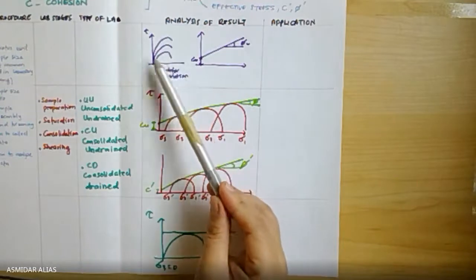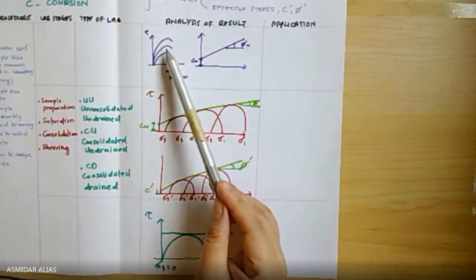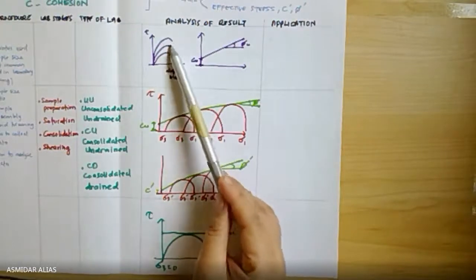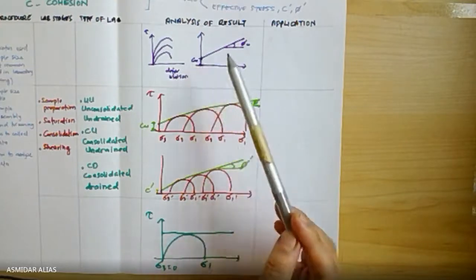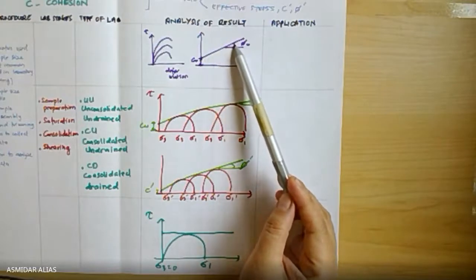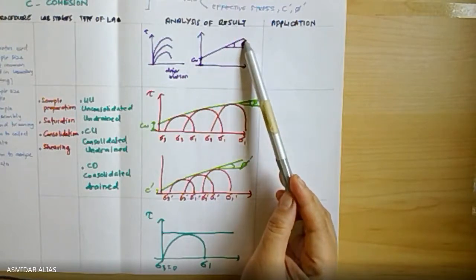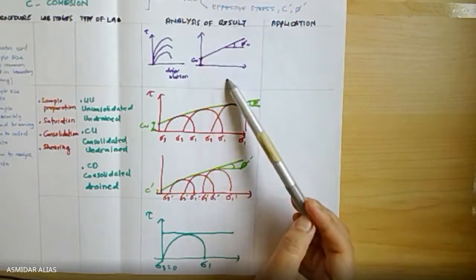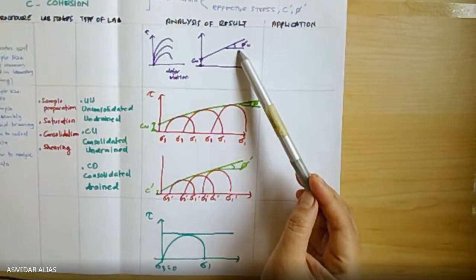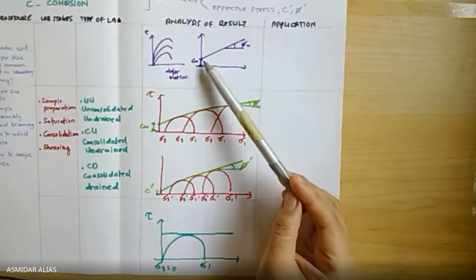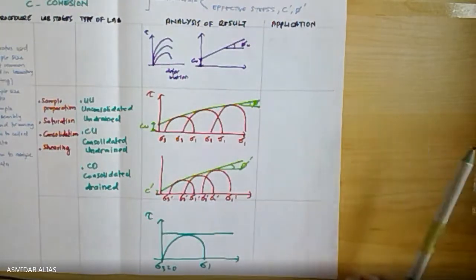So this is for the first test, and then you increase the value for normal stress, and then you increase the normal stress again. Okay, you get different types of deformation pattern. From this data, you can transfer to this shear stress versus normal stress graph, and then you can plot the data. You have about 3 to 4 plots, and from that you can use a linear line to show the relationship between shear stress and normal stress. After you have this graph, we need to find the parameters of the soil. So this will be your phi, the friction angle, and whatever intercepts the y-axis will be the cohesion value. So that one is for the shear box test.